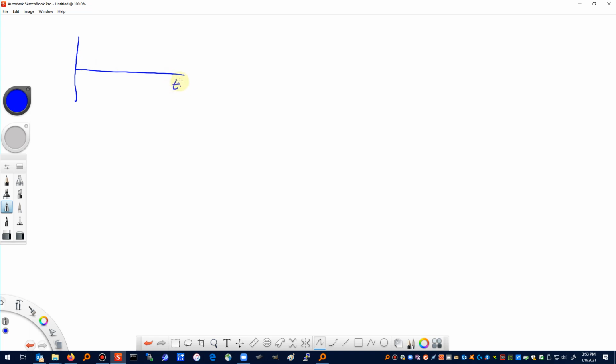So you'll often see me make plots with time on this axis, and just for the sake of having something, let's say that we have a place on our component where we're measuring strain, and we have this time history, and it does something like that. Now on this time history, there's a typical digitization process, something to turn this strain signal, which is a mechanical quantity that's happening on maybe the surface of a component, into a digital time history.